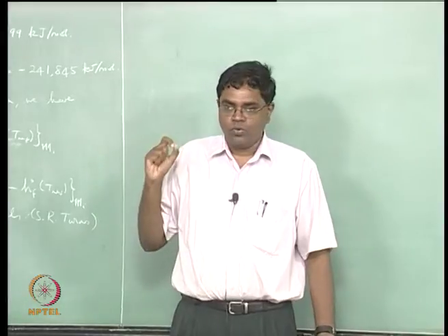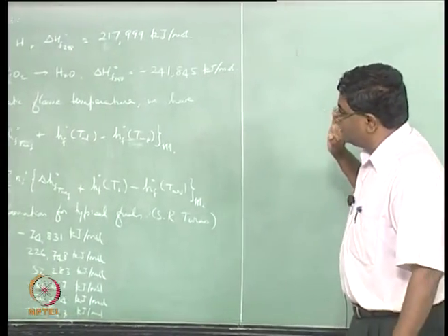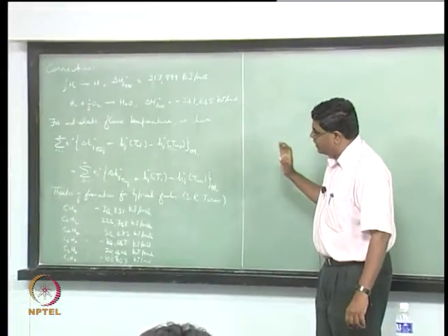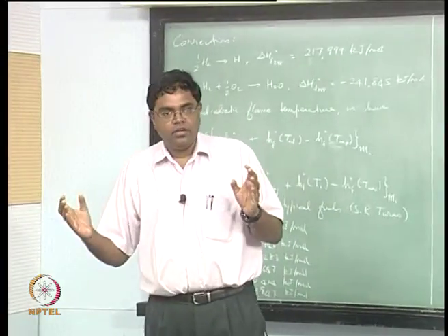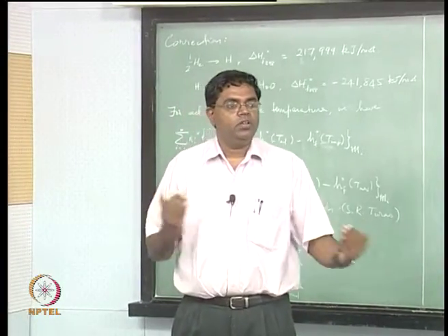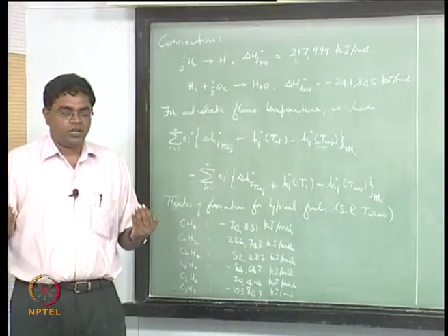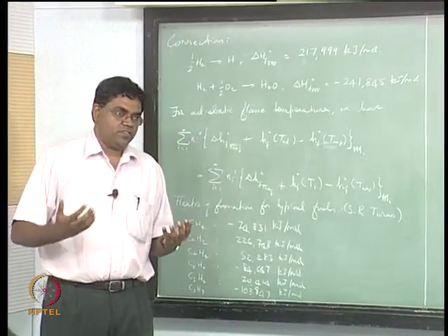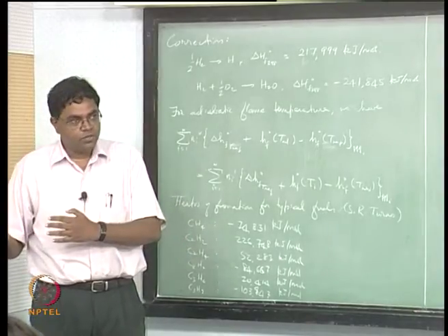Finally, the last point that I want to make here is that this essentially says that all of combustion is all about a transaction between heats of formation and sensible enthalpy. We started out with substances, the reactants, which were low in sensible enthalpy, high in heat of formation.